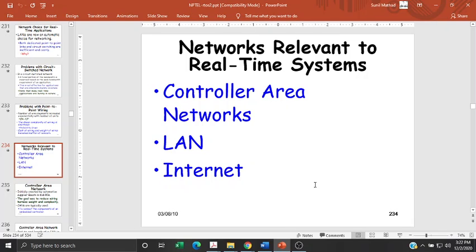With respect to that, there are different networks proposed for real-time systems. The CAN protocol, or Controller Area Network, was proposed by Bosch, mostly targeting the automobile industry. We will be discussing that; maybe you will study it more in automotive electronics rather than the RTOS. We are just touching it superficially, stating that there are different nodes, they are addressable, and you are sharing a common bus at a certain bandwidth. And you are less prone to noise compared to other bus standards.